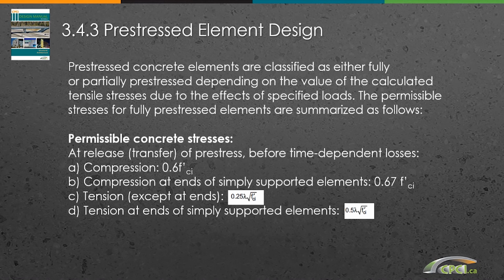We have the ultimate limit state, we have the service limit state at stripping, at the transfer, and at the final serviceability conditions. And then it's a juggling act, depending how we work your numbers around those three stages. And in most cases, the ultimate limit state for pre-stressed concrete is not the case that will control the final design.